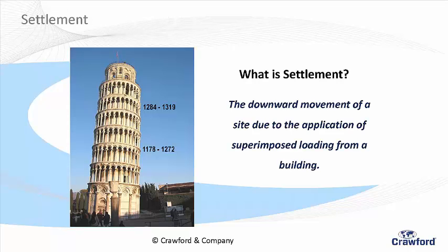So what is settlement? Does anyone want to have a go? If I said subsidence is damage to the site on which the building stands, what's settlement then? Is that the weight of it? Yeah, that was a little bit I put in there, didn't I? Because I said subsidence is unconnected with the weight of the building. This has got absolutely everything to do with the weight of the building. So, when does settlement occur? Exactly. No. It can occur on very old buildings too.